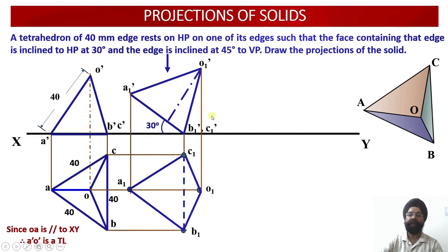So we have discussed one thing, that even though the points B1 dash and C1 dash used to be located farthest away from the observer, they are giving us four edges which are part of the boundary of the object. So that is why these edges will be drawn dark, whereas only one edge on which it was resting will be overshadowed by these two surfaces over there.